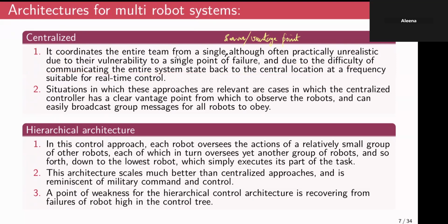It's a long statement, but essentially what it does is that there will be a central server, which monitors the action of all the constituent members of a multi-robot system. So if I call this the server, and if you have a multi-robot system, maybe I'll label them as 1, 2, 3, there will be a direct flow of communication from the server to the member robots. The communication among the member robots could depend on whether they are weakly cooperative systems, strongly cooperative systems, or collective swarm systems. But in case of a centralized system, there will always be a direct line of communication from the server to the constituent robots.